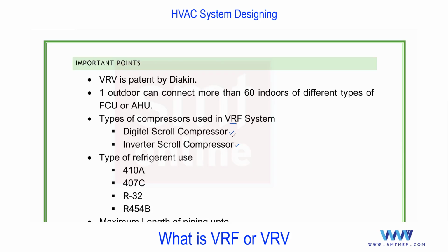And as a mechanical person, you know the different types of compressor, no? Screw compressor, scroll compressor, reciprocating compressor, etc. But remember, in VRF we are using the scroll type. And even in split systems with the inverter type, you'll find scroll. Now many vendors, even in split, are using scroll because from the noise point of view or efficiency point of view, we have advantages. So as a mechanical person, I believe you know what a scroll compressor is, right?